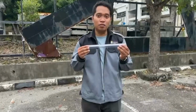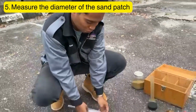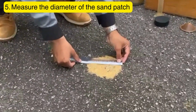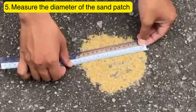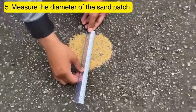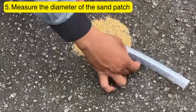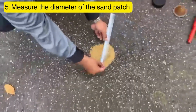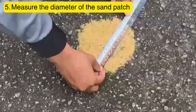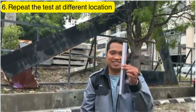Using this ruler, we have to measure the diameter of the sand patch at 5 different angles. First angle, 15 cm. Second angle, 14 cm. Third angle, 13.5. Fourth angle, 14.5. The last angle, 14 cm. Lastly, we have to repeat the test at 3 different locations.